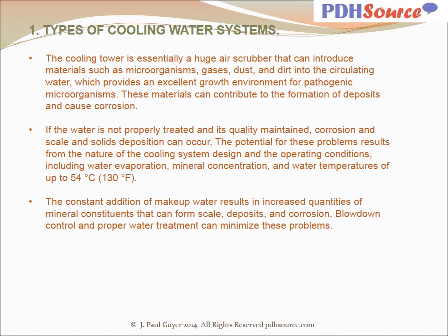The potential for these problems results from the nature of the cooling system design and the operating conditions, including water evaporation, mineral concentration, and water temperatures of up to 130 degrees Fahrenheit. The constant addition of makeup water results in increased quantities of mineral constituents that can form scale deposits and corrosion. Blowdown control and proper water treatment can minimize these problems.